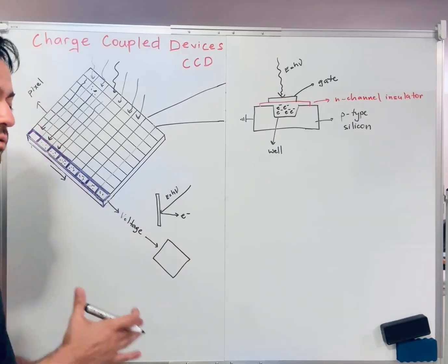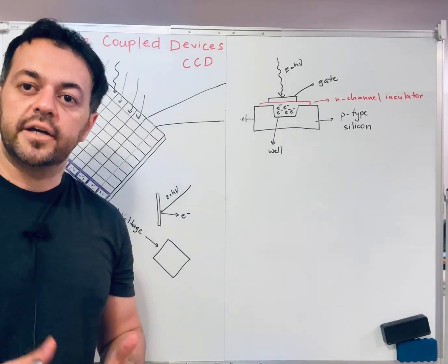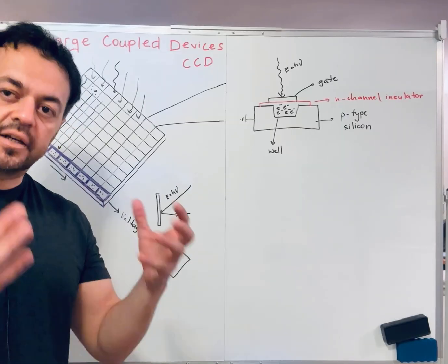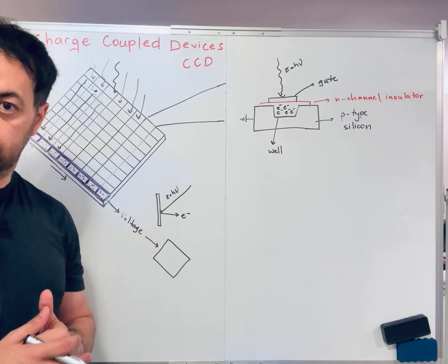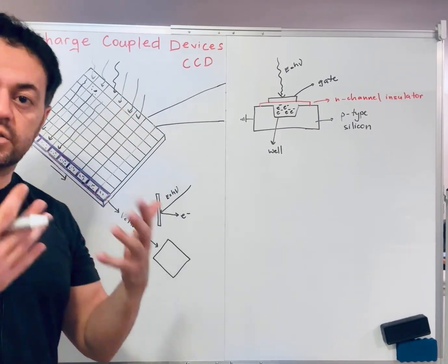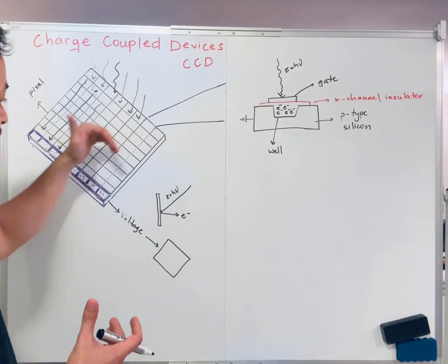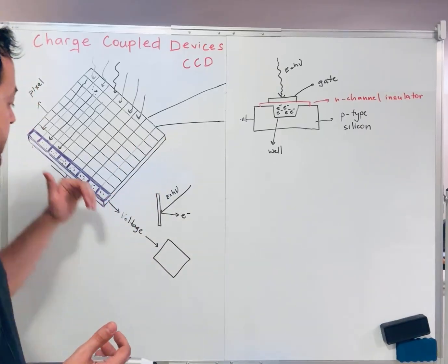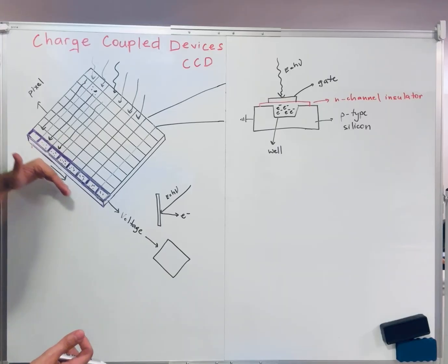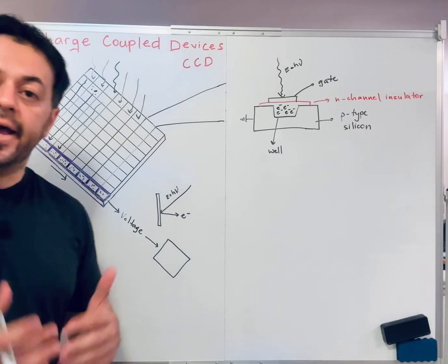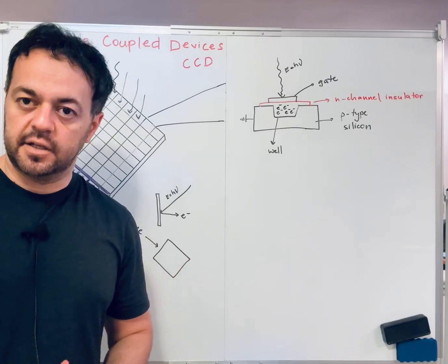So the important part of this CCD is how exactly it collects the photon and transfers the collected signal towards the detector, towards this readout. First it collects it, converts the photon into electrons, then the electrons are dragged across the pixels, and at the edge they are transferred horizontally towards the analog to digital converter, which eventually produces the signal.